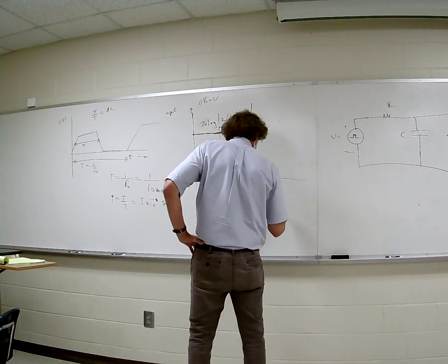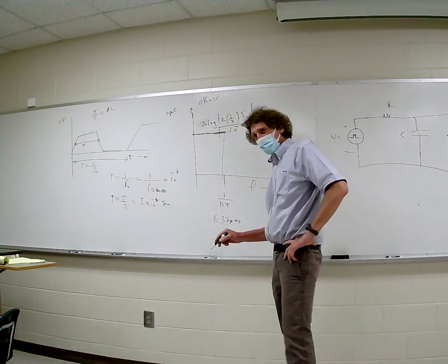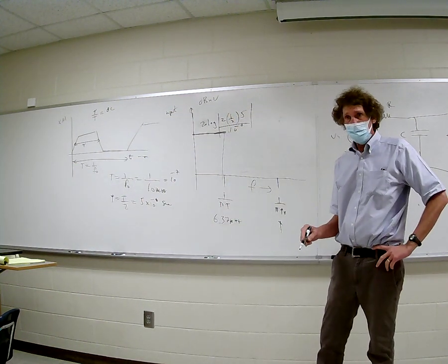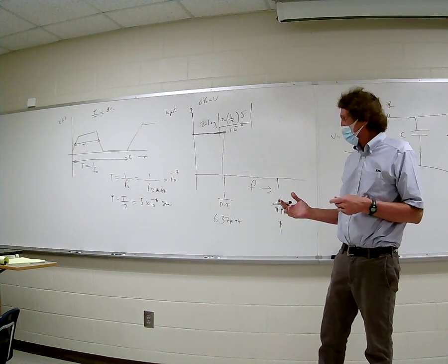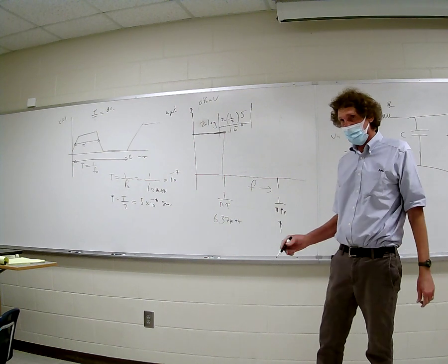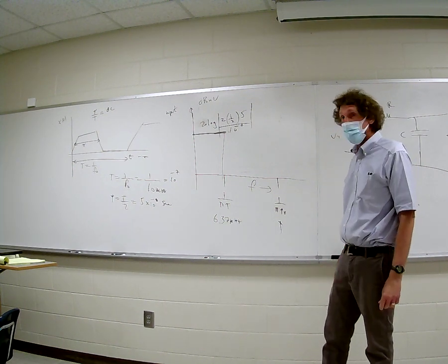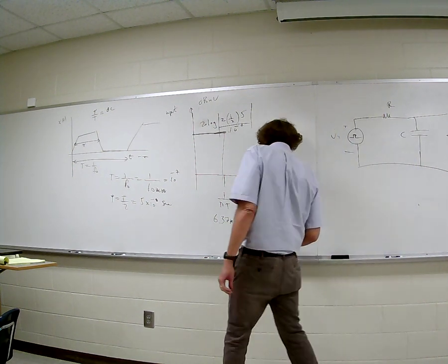All right, where's this one? The rise time was 10 nanoseconds, is that right? Yeah. You see how that had nothing to do with the first problem at all? So what's this going to be? 1 over pi t rise: 31.83 megahertz. All right.